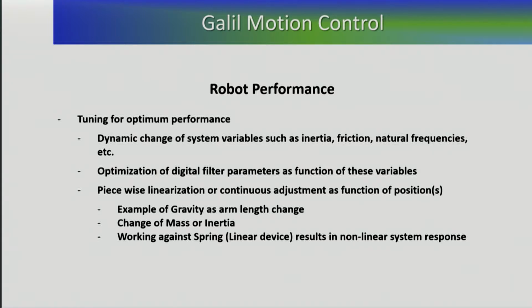So you have the ability to define the relationship and choose one of two options: either select the PID parameters at different levels and linearize between those, or define some type of mathematical function that allows me to control my PID coefficients as a function of theta operation.